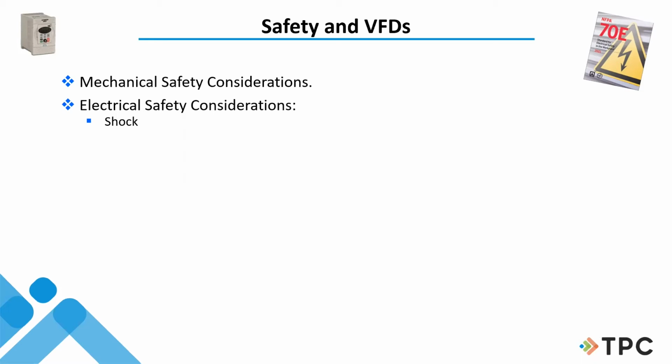And standing on a concrete surface is considered grounded. So think about what you're leaning against. Think about what you're standing on. Do I need dielectric pads? Do I make sure the gloves I have on, what is the voltage? I need to know 70E and follow your electrical safety program to make sure that I don't get shocked. I guess a good one is probably just turn the power off. That's a good one.